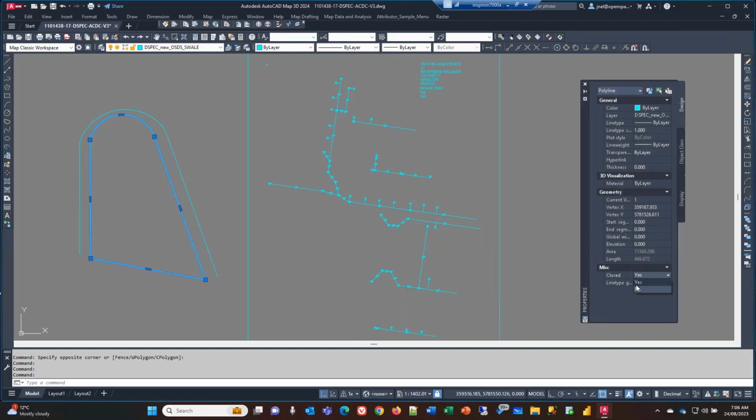So let's say we look at, for example, roads, and you now have a polygon area, but now let's say the curves may come back on itself. If you are going to handle it programmatically, the curve could then act as a polygon that you can fill, which is probably something you don't want. So that's the area you have to look at: are you actually going to snap it closed, or are you going to use the attribute whether it is closed or not? It will be handled differently programmatically.